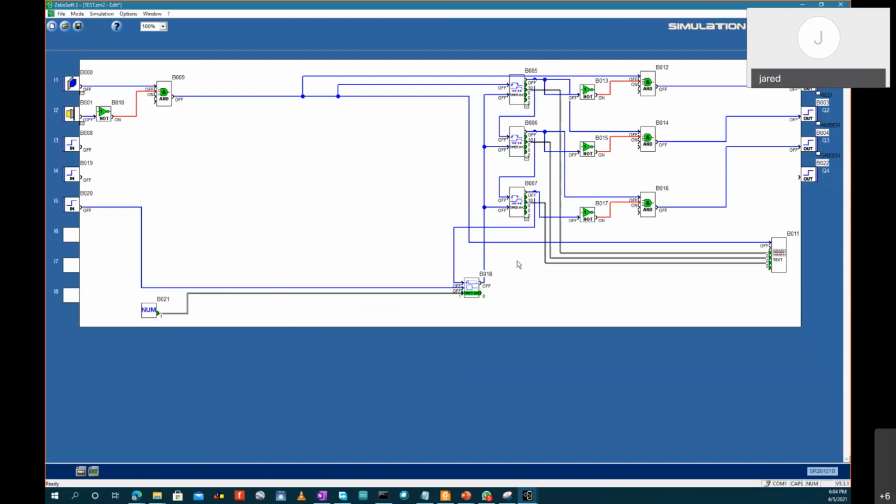So it's better for you, if you're saving something, save as a version 1.0, so that you can trace back to the last one that worked well. You can pick that one, check where the problem was, and modify. In advanced PLCs, you can save them as versions and you can do comparison. It will tell you which block changed and how it changed.